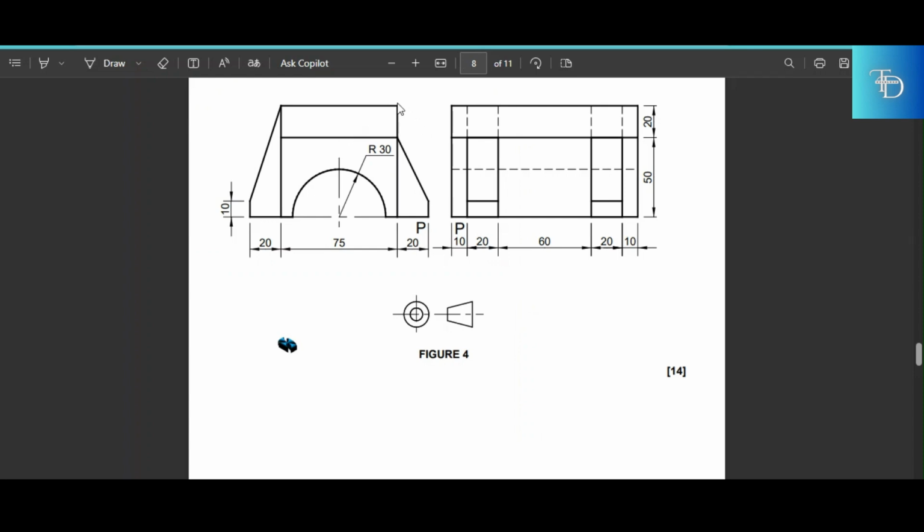Some of you will say that is the top right corner. Well, yes, it is the top right corner as a given view, but for the whole component, the top right corner is not that corner. It's somewhere there. If you extend this horizontal line and then from this corner right here, push this vertical, it's gonna meet with the horizontal that you extended. Somewhere there, that is gonna be your top right corner for the whole view.